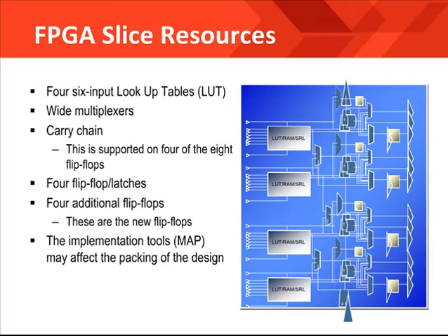The carry chain is also supported on 4 of the 8 flip-flops, and there are also dedicated muxes which can be used to build larger multiplexers and save LUTs for your system to get higher speed.